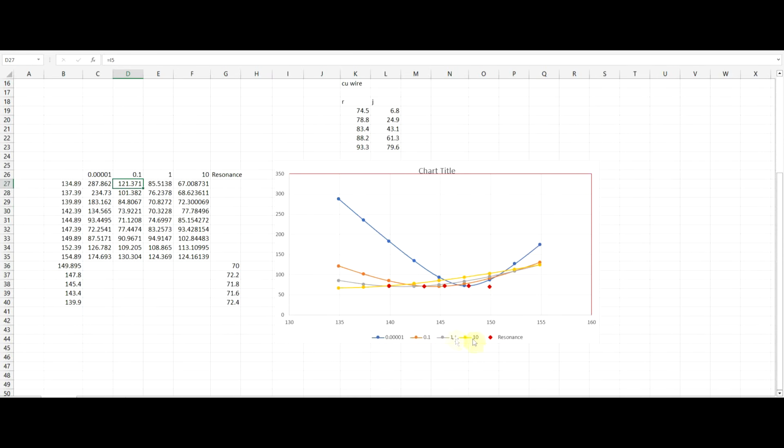And for the other thicknesses, it's not really obvious, because the frequency interval at which I looked is too small. But anyway, as the thickness increases, so does the bandwidth. And another thing you can notice is that the resonance point moves slowly to the left. So we have our direct length conversion frequency at around 149.89 MHz, and then with the actual simulated structures, we can see that frequency decreases as thickness increases.